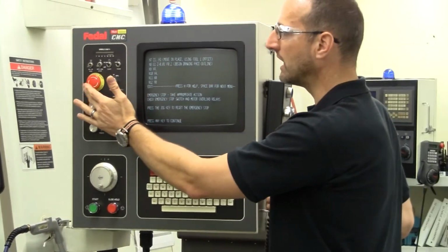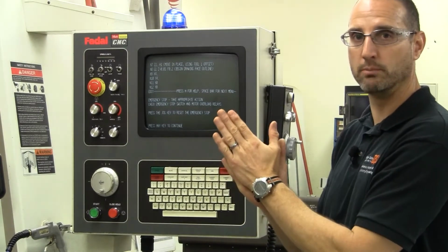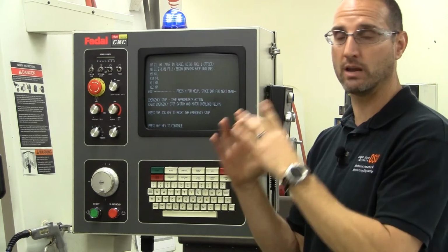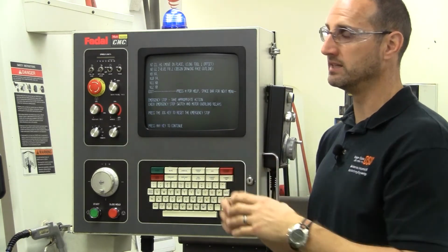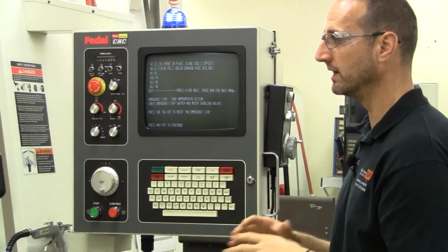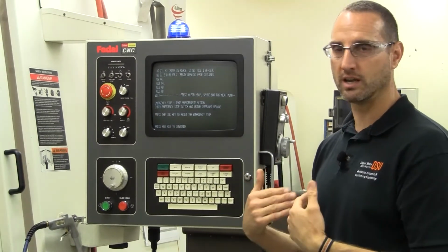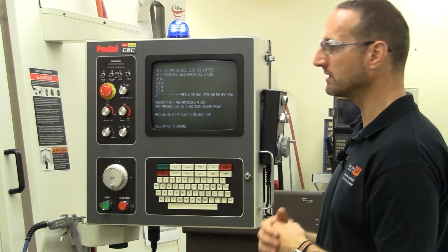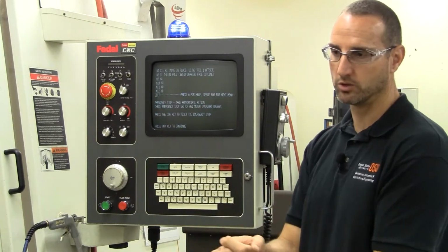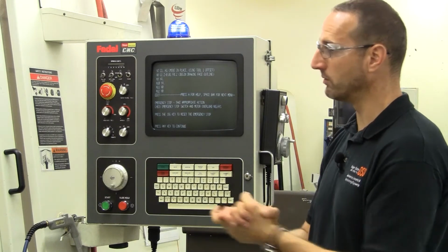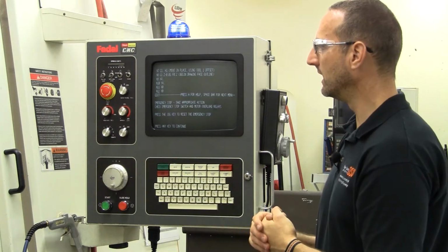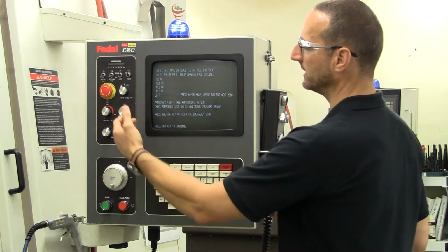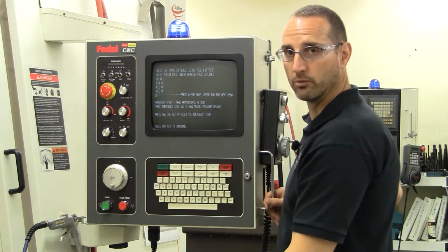Recognize when I push the E-stop, it will latch itself in, meaning once I've pushed it, it's going to stay latched in and keep the controller in emergency stop mode until I release it. That's just to ensure that everything is safe on the machine and you as the operator have determined it's okay to proceed from that point. If I had crashed the machine, maybe I've buried the tool into my part, I want to make sure that everything is safe before I release the E-stop and start moving things around again. So let's walk through how to release the E-stop.